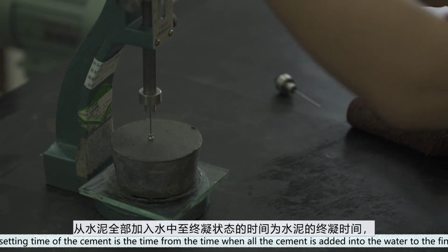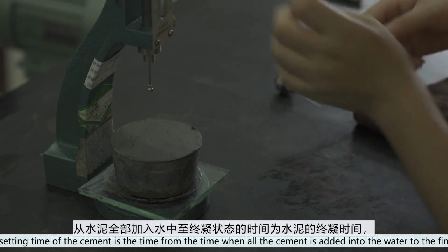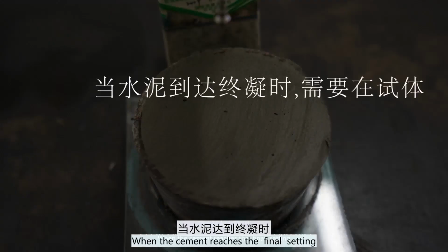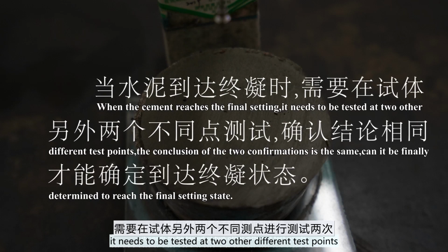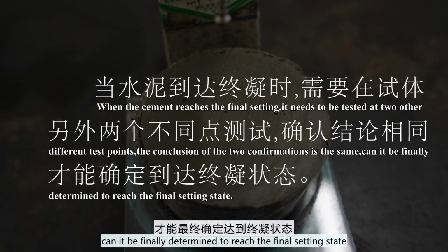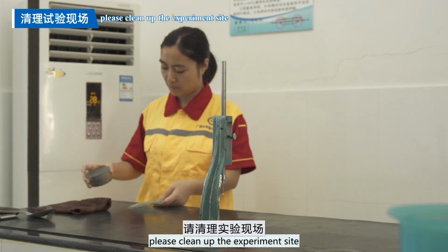The final setting time of the cement is the time from when all the cement is added into the water to the final setting, expressed in minutes. When the cement reaches the final setting, it needs to be tested at 2 other different test points. Only when the conclusions of the 2 measurements are the same can it finally be determined that the final setting state is reached. After the experiment, please clean up the experiment site.